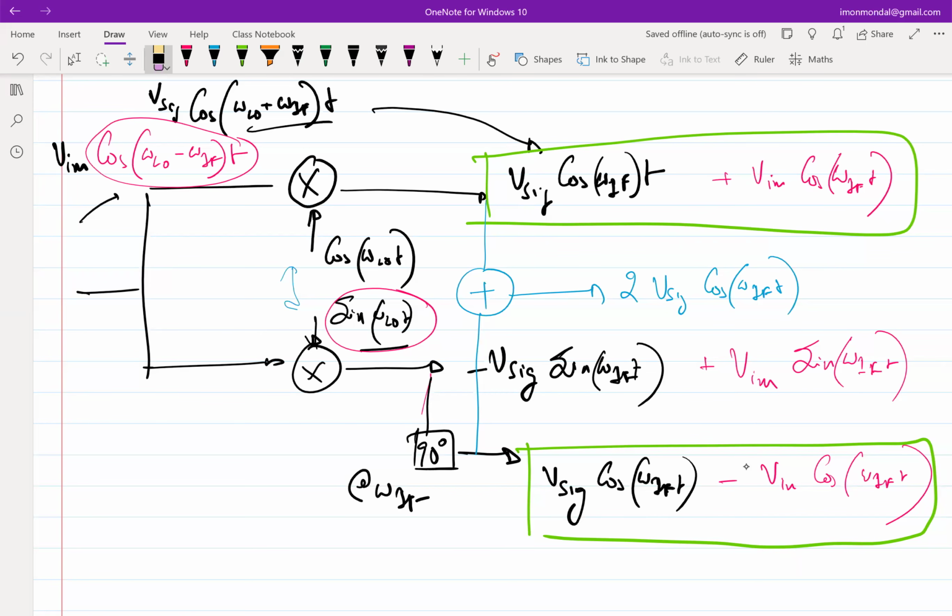I say burden because, if you do not cancel it, forget about the noise: if there is a signal at the image, that signal is going to cause distortion to all the active components through which it flows. So it is better to cancel it upfront and not wait for digitization later on. But that's again a topology choice.